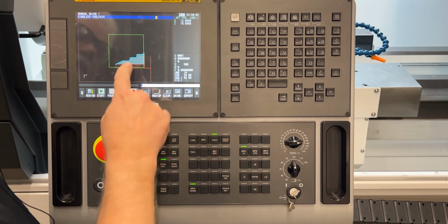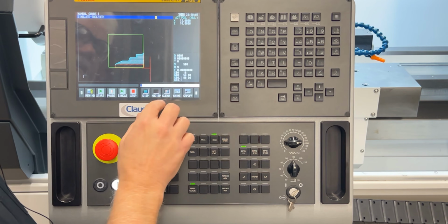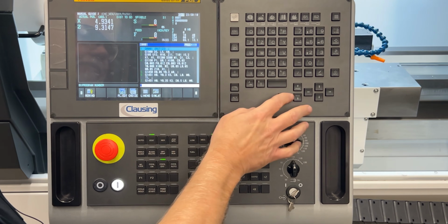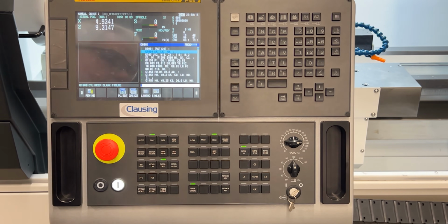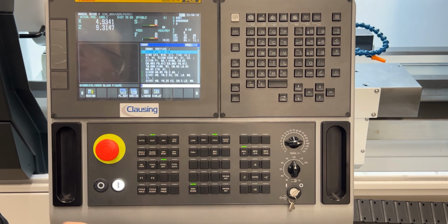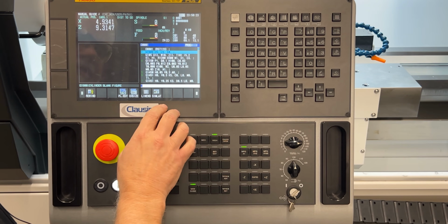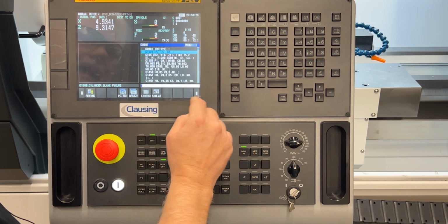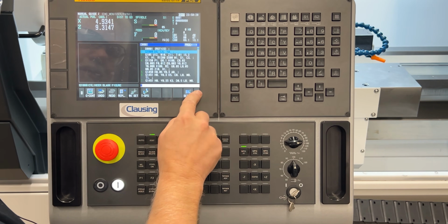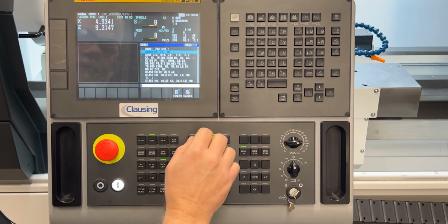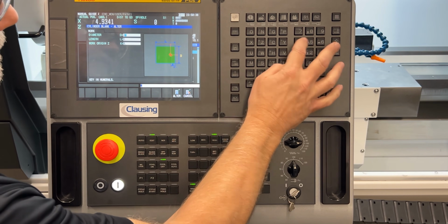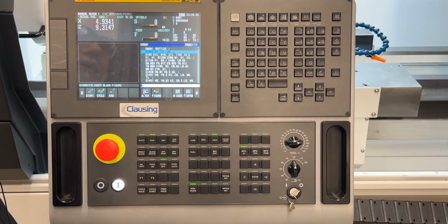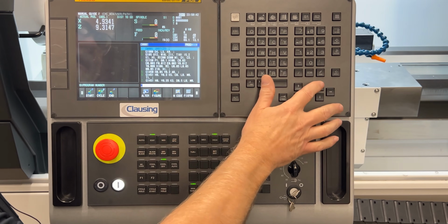Okay. The only difference is my green box, because the part that I created I used a 5-inch diameter instead of the 4-inch that the actual part is. So it just looks bigger than the actual part. If I wanted to alter that, I could go to alter, which pulls up that information. I'm going to go back to, let's say, 4-inch diameter on that. Hit alter again. The information will be updated.